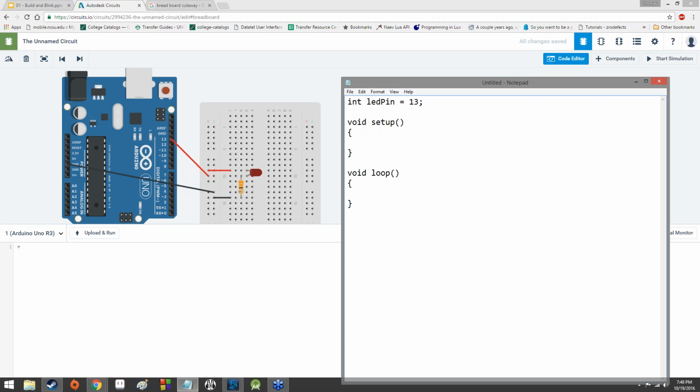So now that we've done that, let's go ahead and stick our first command inside of void setup. This is going to be this whole mess right here. pinMode(LED_PIN, OUTPUT). Notice how the M in pinMode is capitalized. Notice how we've got pinMode, no space, open parentheses, no space, LED pin, just like we have it up here, comma, I put a space here, you don't have to put a space, and then OUTPUT, all capitalized, closing parentheses, semicolon.